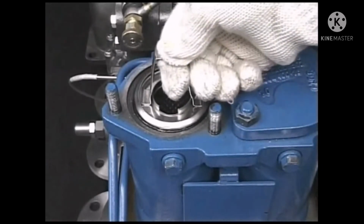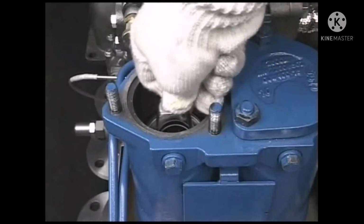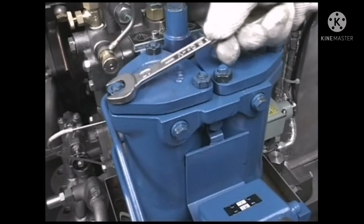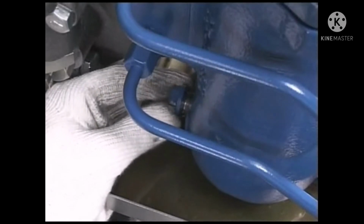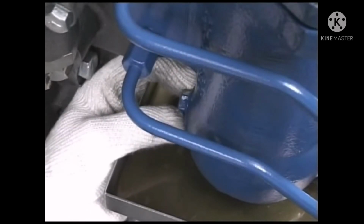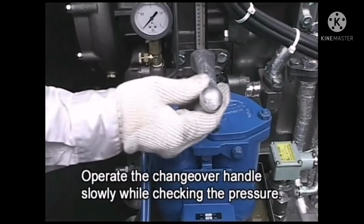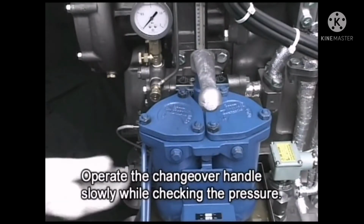Reassemble the fuel oil strainer in reverse procedure to disassembly. Finally, return the changeover lever to the use position of both sides and bleed the air. This completes the work.